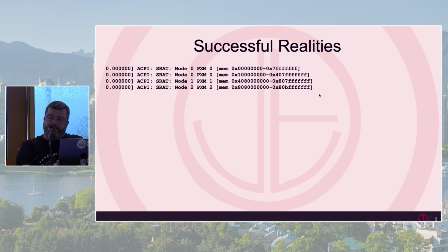And it is a type 2 device with memory, right? So this is actually how it would show up. The system BIOS goes out and maps it all, says, hey, I found a mem region on a device, and I'm gonna map it into your physical address map. So you can look and see, okay, this is a 2-socket system, 2 NUMA nodes. Node 0 is mapped to these physical addresses. Node 1 is mapped here, and then node 2. So this weird node 2 is this, and if you did the math, this is 1 gig of RAM.